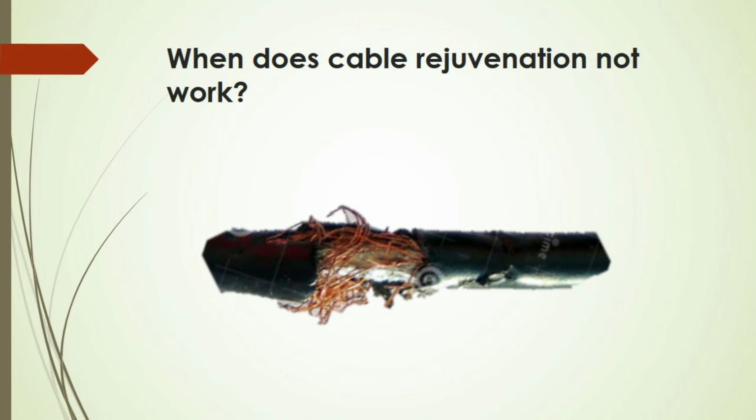Some circuit owners began employing strand block cables in the mid-1990s to prevent water from migrating longitudinally in the strands, and unfortunately, this also hinders the process of rejuvenation.